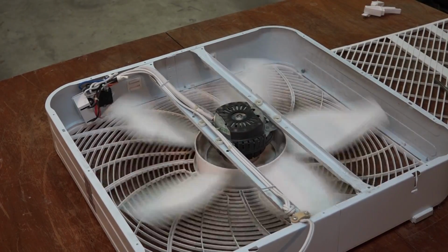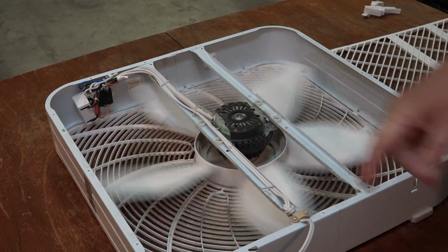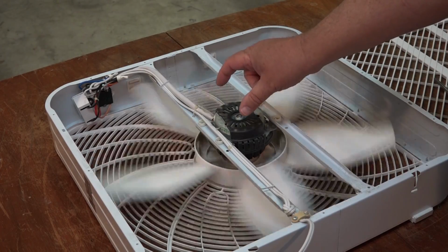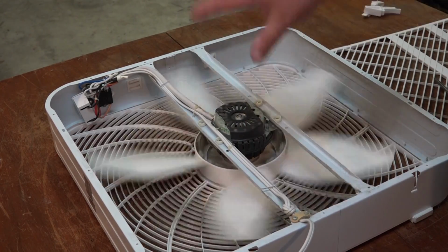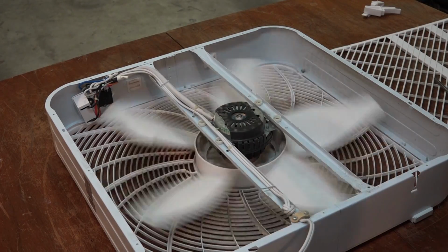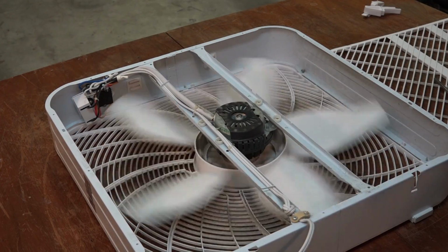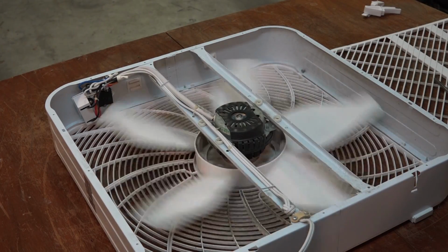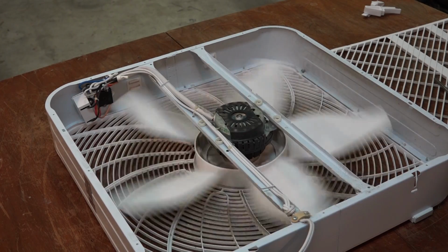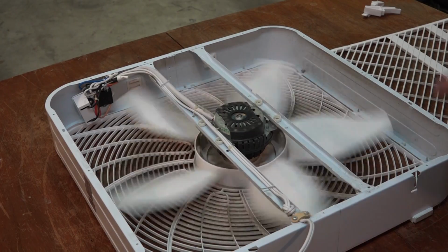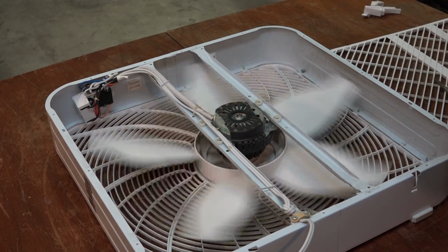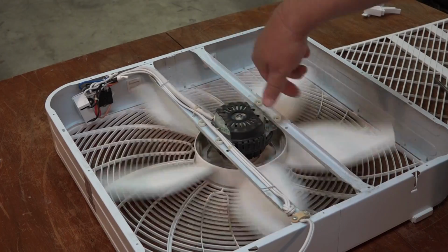And that's due to, we have two coils, as I showed on the diagram. We've got our electrical energy going through the main coil, which is allowing the fan to spin because we've already started it, but our auxiliary coil is not energized, so we don't have our leading or lagging phase. You need the two coils energized 90 degrees out of phase to create a rotating magnetic field.